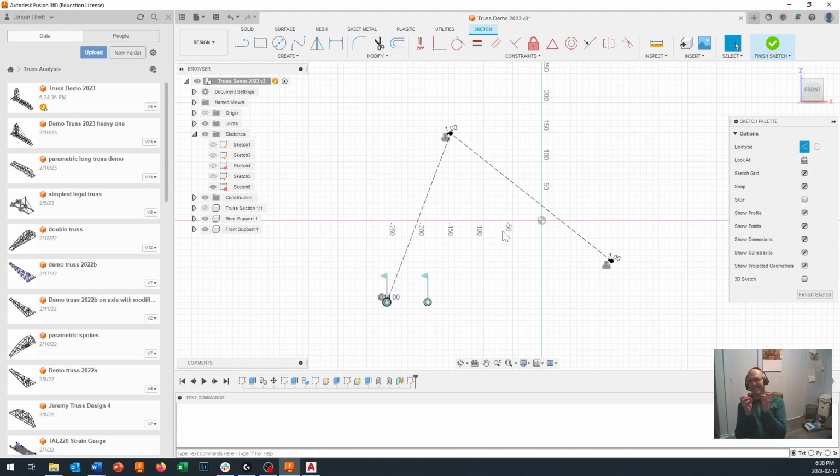Now, this is going to be a little bit inaccurate, but it's still good enough, I think, to work. Because obviously these are perfectly straight lines, which means that you've got that string tension so that it sits in a perfectly straight line. I think a very slight, like a 1 millimeter arc right in here and a 1 millimeter arc right in there would probably simulate your slightly loose lines that you put in there a little bit better. But I've done some testing and this isn't too bad, so I'm going to stick with that.